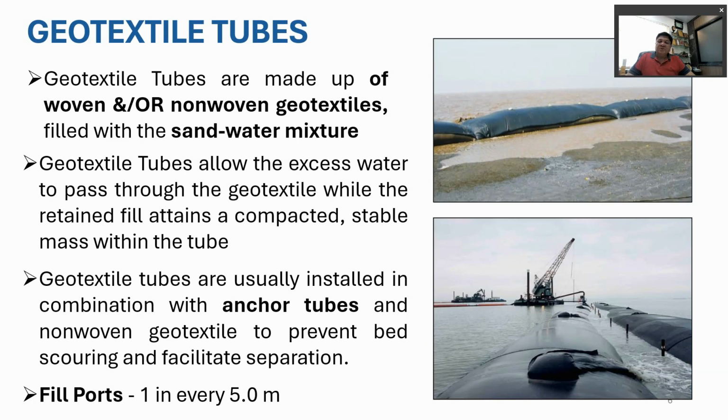Generally, anchor tubes are also considered for scouring purposes, and filling ports are provided every 5 meters to fill the tubes effectively, with proper pressures from the pumps.